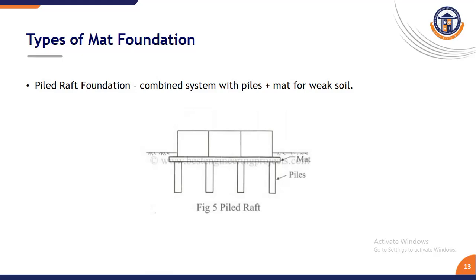Generally flat plate is used for small office buildings, and beam mat is generally recommended for commercial buildings, and cellular mat is generally recommended for nuclear power plants or very heavy industrial complexes. And finally piled raft will be recommended for the IT park in Bangalore or any other places where clay soil needs extra support.